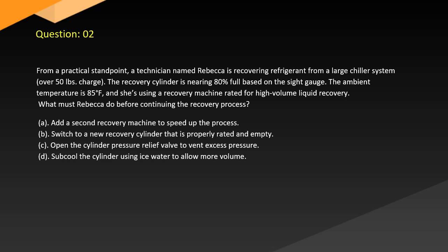A. Add a second recovery machine to speed up the process. B. Switch to a new recovery cylinder that is properly rated and empty. C. Open the cylinder pressure relief valve to vent excess pressure. D. Subcool the cylinder using ice water to allow more volume.